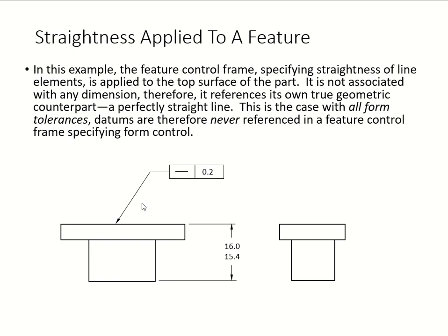In your summary table in the Unit 5 lecture, there's a table for form tolerance, and the very first one is straightness, which is a little line. So make sure you consult that summary table. There's no dimension, it's just showing you the height of this thing, and this is a tolerance of that height.